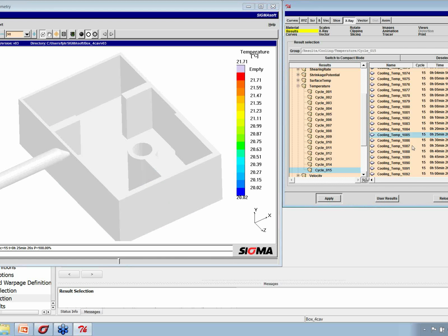Now I typically apply, so I've gone 30, 35, 40. I've applied some additional time steps here just in case. Like I showed you that one example with the PBT where it took an hour. So I typically always do an hour. And then at least I can always say, well, really at 25 minutes is when it's solidified. But I want to make sure I capture that time step. And then, of course, in the PowerPoint I showed you at 25 is when our displacement finally stopped changing.